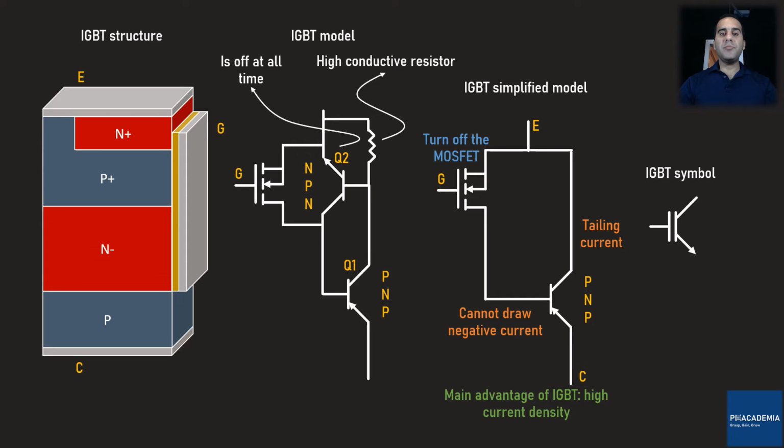Another drawback of the IGBT is that the MOSFET must tolerate the same blocking voltage as what the BJT does. By taking the base current passing through the MOSFET into account, we soon notice that the MOSFET occupies a large space on the die despite the fact that it handles around 1/10 of the total current. This implies that in low to mid-range power conversion applications, we cannot achieve a satisfactory volume density. However, for high power applications, we definitely can achieve a better volume density than what power MOSFETs can offer.